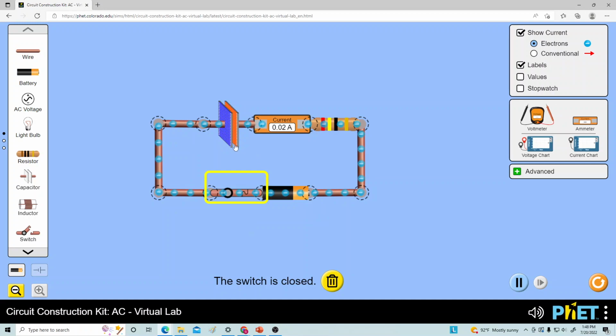Well, it has to do with the interaction between the capacitor and the battery. The capacitor and the battery are the two things that are mitigating all of this. The battery wants to push the charge and follow Ohm's law with the resistor, and it wants to push 2 amps through this circuit. But as the charge gathers on the plates, as one of the plates becomes positively charged and the other plate becomes negatively charged, you can't draw as many charges off of one plate and put them on the other plate.